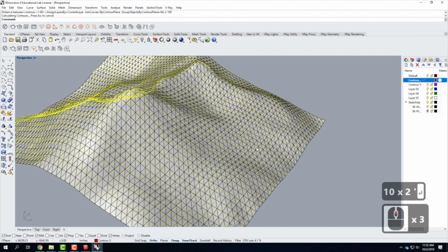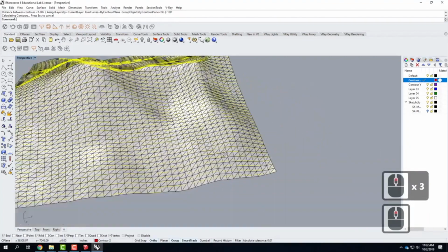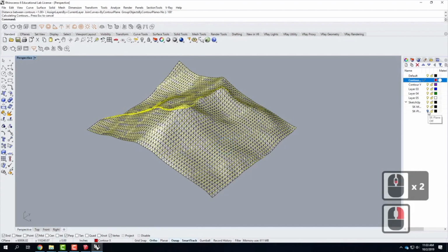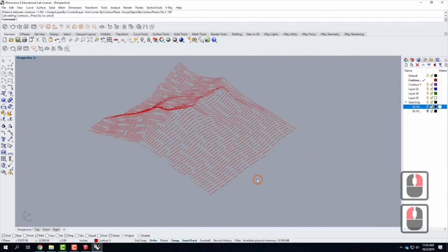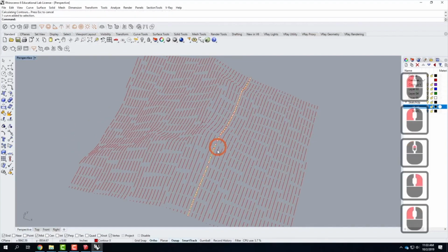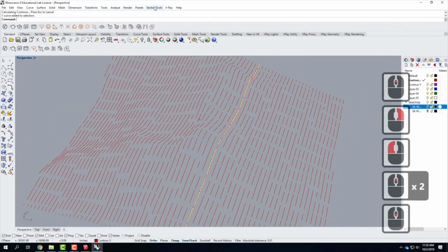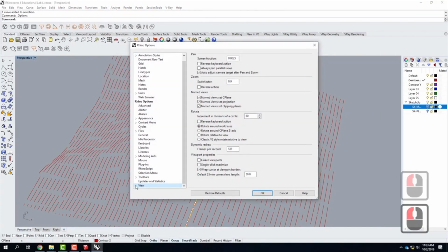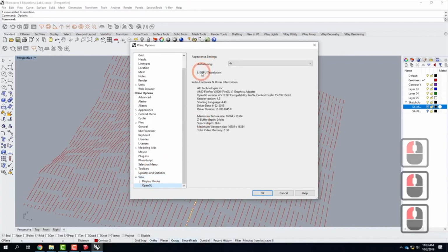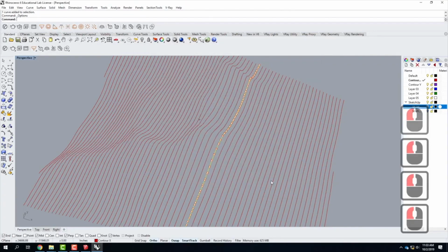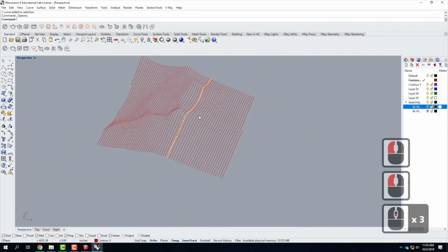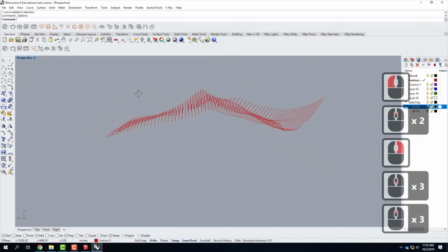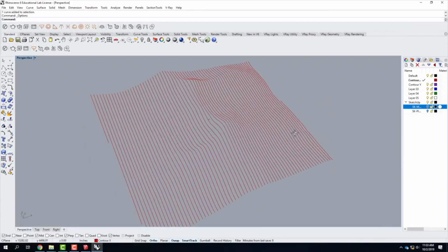And so when I do it, it's going to give me a bunch of parallel lines, a bunch of curves, right along the surface. Let me turn off for just a second the SketchUp mesh so that you can see this a little bit better. Well, that was not useful. Oh, I forgot, sorry. I have my OpenGL tessellation turned on. Now we can see them as nice smooth curves. So what we should see is a series of nice curves that then go along and represent the surface.